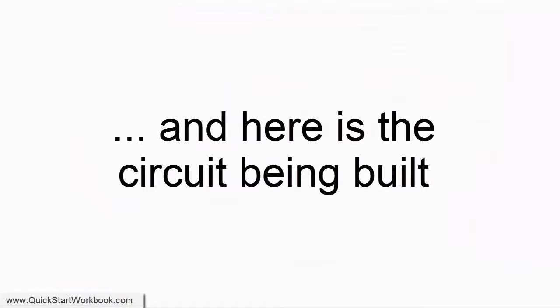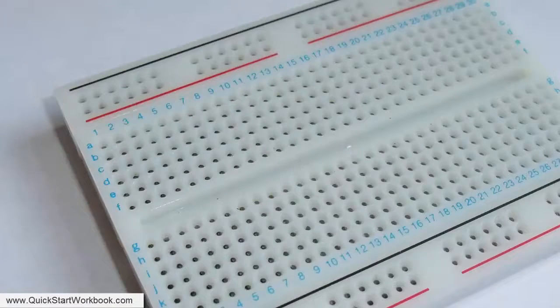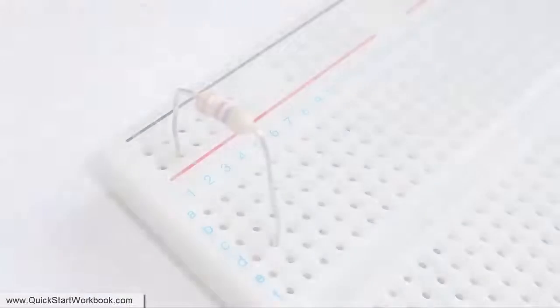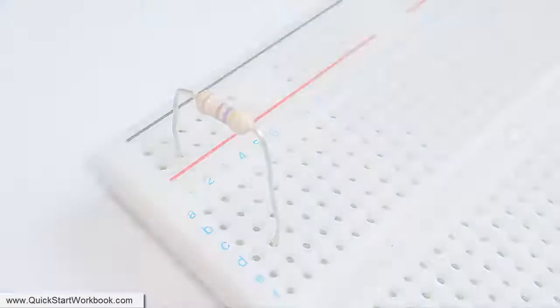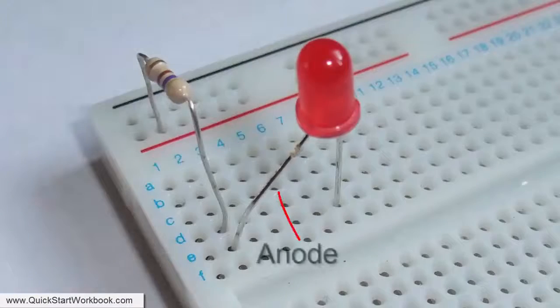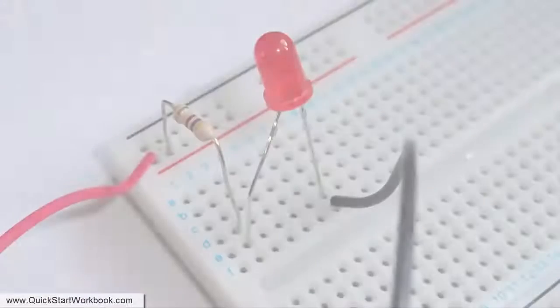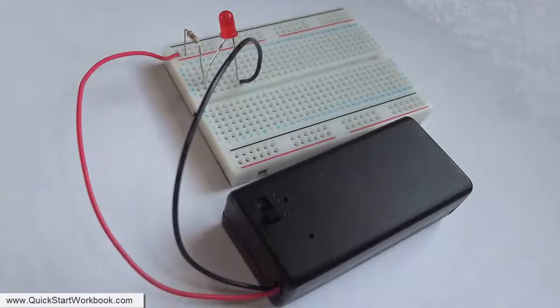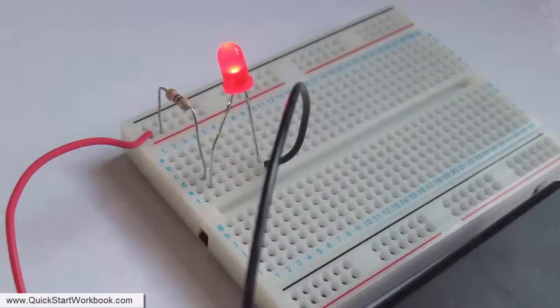And here are a few photographs that show the actual circuit being built. So we start off with an empty breadboard, and then the first thing we can do is to add the resistor. Then we can add the LED. Here again I've labelled the anode this time, which is the long terminal, and also the cathode. And finally we can complete the circuit by adding the battery, so connecting up the positive terminal and the negative terminal. And it works. Fantastic.